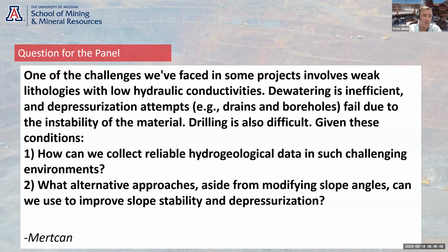It doesn't have to be large scale. If it's low hydraulic conductivity, then you can get away with an NQ and HQ diameter borehole with drill and drive, where you install the casing either through the drill string or on the outside, and then make sure that the casing is perforated to allow water to drain in. You can then use that hole to do BMR surveys if you use PVC, because you can do that through the PVC. If you hit enough water, that hole can serve as a drain, or you can get a VWP installed in it.